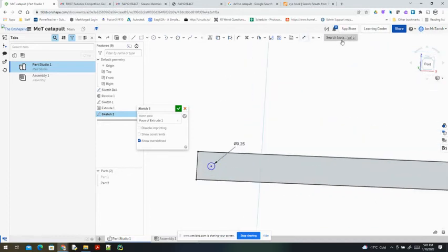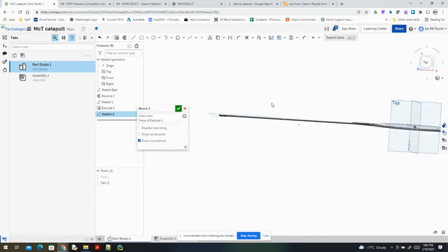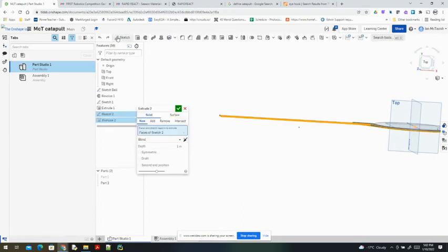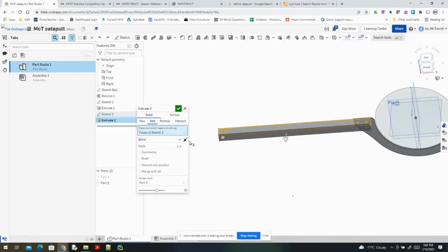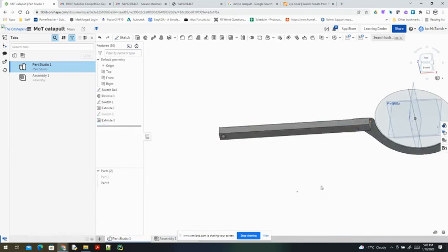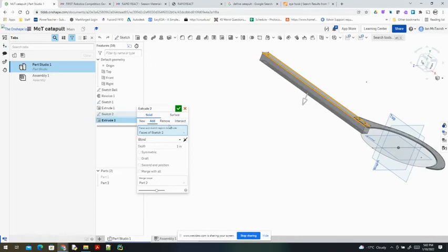this will be my pivot point. So there's going to be a lot of force on this, so I think I'll do a half inch, and then that way I can put a bushing in. So there's my shape, 1 inch. And you can see I've all of a sudden got this started, and